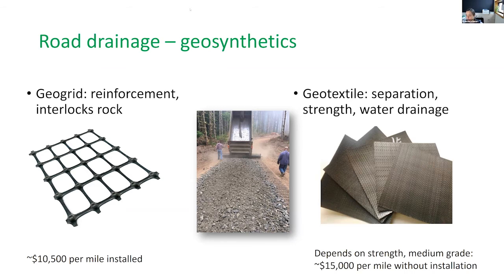Oh, because of the amount of moisture there is in the subgrade. So if you have saturated soils during the winter time, you are not able to really compact that subgrade. There's a certain ideal amount of moisture that different soils have in which they compact the best. So if that soil is already saturated, it will never compact well. For example, if you have a clay soil, and if it's saturated and wet, if you just put clay on your hands, it's like Play-Doh, right? So you will never be able to achieve the level of compaction that you need to be able to kind of seal that surface. Does that make sense?